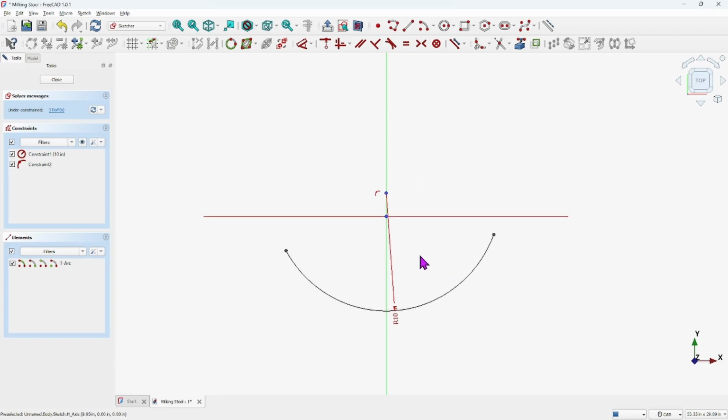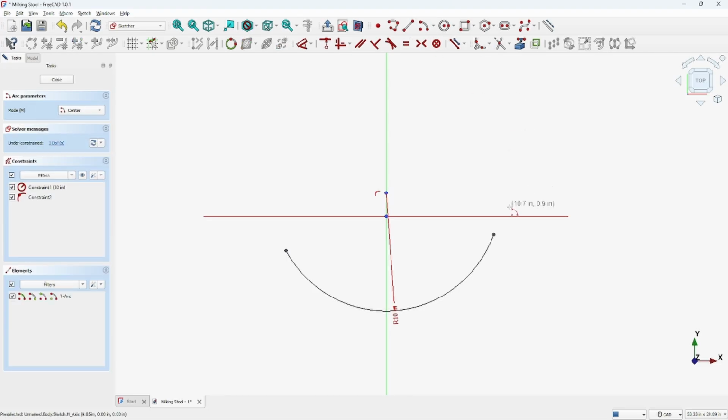Now I want to put a 5-inch radius over here along this x-axis. Okay, I'm going to right click because I'm not 100% sure I tagged that line. Right click to get out of it. So I want to make sure I'm on that line. That's important. There you go. And we know that is 5 inches. Typed in 5, hit enter, and then I'm just going to put 0.1 there, swing it around to here.